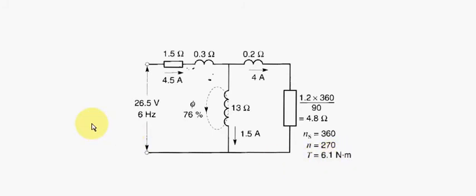And the reason being is the volt drop across this resistor here is now significantly large enough to have an influence against the volt drop across here. So we are unable to maintain 1.9 amps.